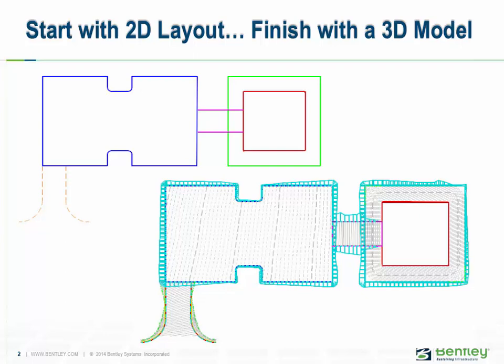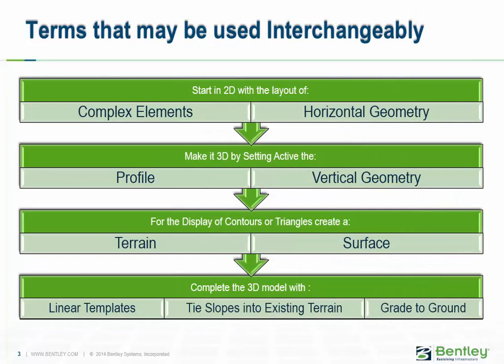We'll be creating a building pad surrounded by a yard or apron, as well as a sloped parking lot, sidewalk, and driveway elements. For clarification of terms, a lot is a shape that may be level, sloped, or otherwise graded, versus a pad shape, which is always level or flat. The yard or apron is the area between your pad or lot and the offset boundary shape. For drainage, the yard is generally sloped away from the pad or lot.